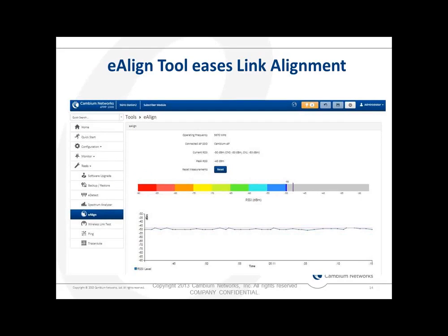And once the radio links up initially with the master, it's got this graphical screen here that shows you the received signal strength indication, and this gets updated every half second. So it gets updated very rapidly, and so you can look at it when you're trying to do that fine alignment of your point-to-point radio in order to optimize it.